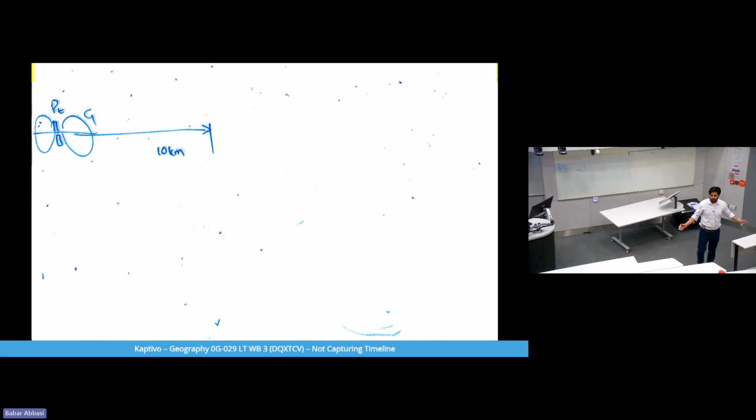It means it is radiating well at a given gain G in this direction. Because of the transmit power available here, it can reach up to 10 kilometers. After 10 kilometers, its energy will go below the noise floor, and any receiver beyond that will receive nothing.